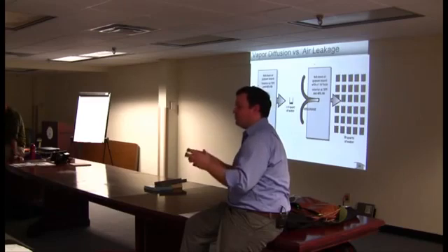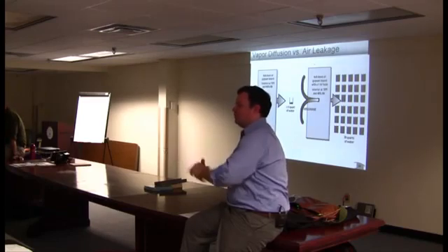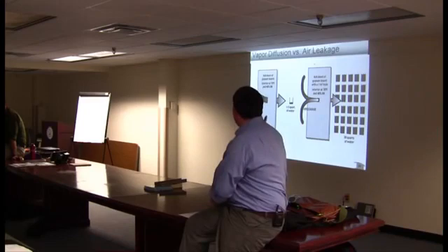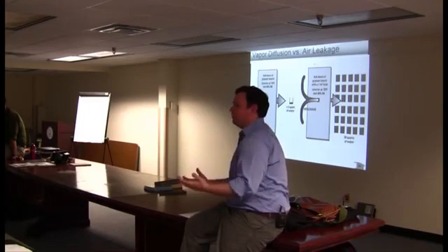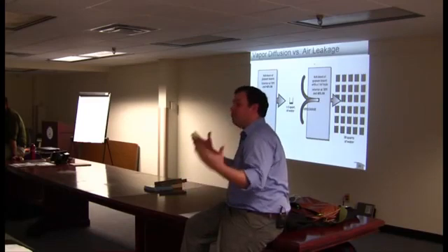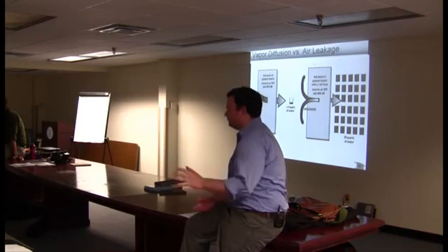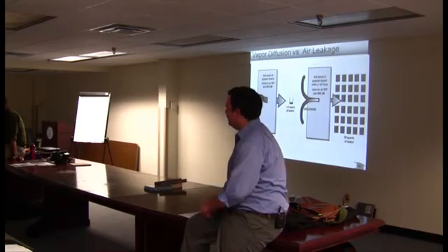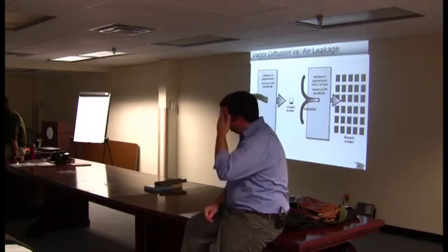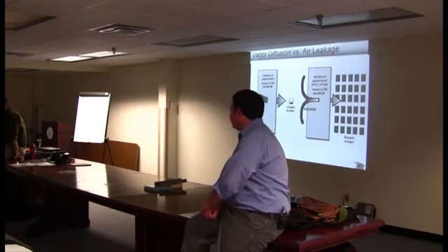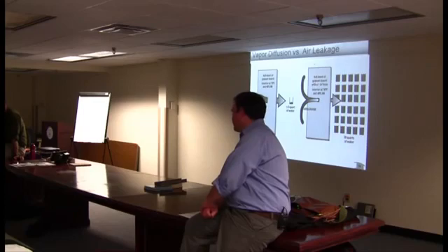So basically, how much moisture is going to work its way through at the molecular level, and we're looking at about a third of a quart of water over a heating season. Does that seem like a lot of moisture for your HVAC system to have to take out of the air? Well, no, it's going out of your building in this case. Okay, so relatively small in terms of the entire five-month heating season, whatever it is. That's not a lot of water vapor diffusing across just an unpainted piece of gypboard. And of course, when you paint it, it'll be even less.